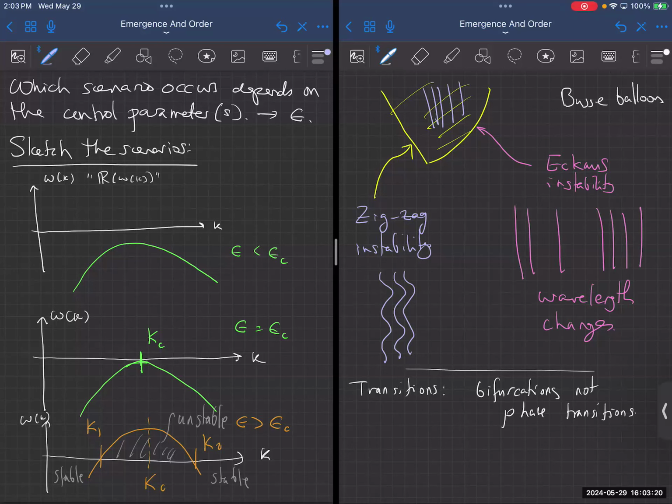Okay, so that can happen. That's just solving the Navier-Stokes equations on a computer. That mode, however, is generated by the turbulence, but it rotates the turbulence and shears it and makes it more isotropic. So the turbulence creates the mode, and the mode then destroys the turbulence. So there's an activation and an inhibition. These two modes behave so that something activates and something inhibits.